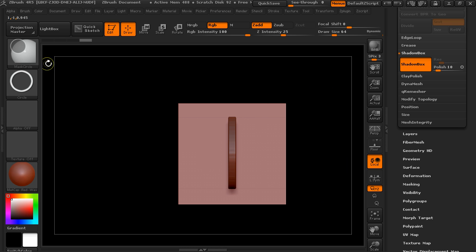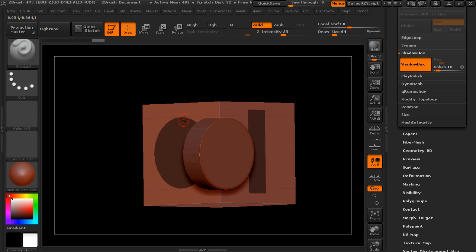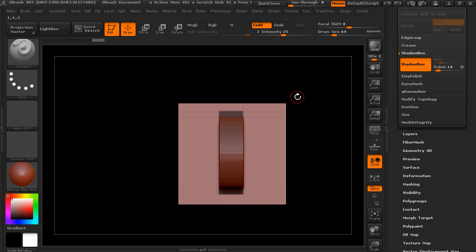Okay, for the thickness, we can come back in with our mask pen, and dragging outside, this will give us the rectangular marquee, and we can create the thickness of it. So if we want it to be a little bit thicker, and remember that it's using the combination of that, so even though I've extended that mask out beyond, it's only taking into account the intersection between this projection and this projection, and figuring out what that actually looks like. Okay.